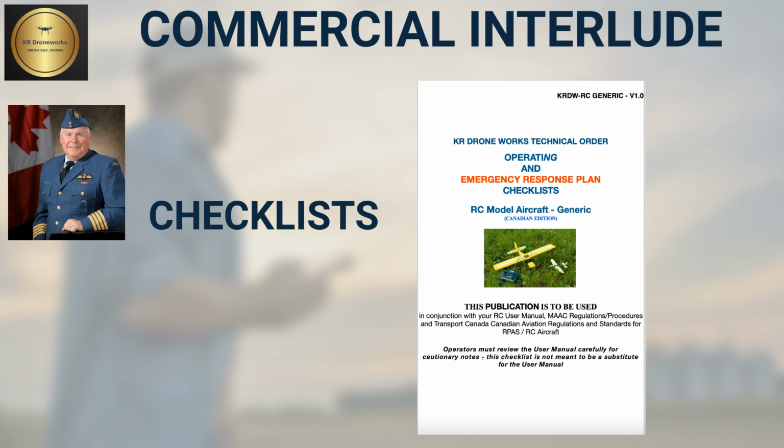Other pilots choose to use the checklists that are available with the purchase of certain apps. Again, for the most part, these checklists meet the minimum requirements, depending on the type of aircraft being flown. The problem is that most pilots do not take the time to modify these checklists to meet the requirements outlined in CARS 901.232. By this I mean, they fail to modify the checklist to include the manufacturer's instructions with regards to operational and emergency procedures, which is a mandatory regulatory requirement, CARS 901.31 and 901.232. This can constitute a review failure depending upon the severity of the omission.